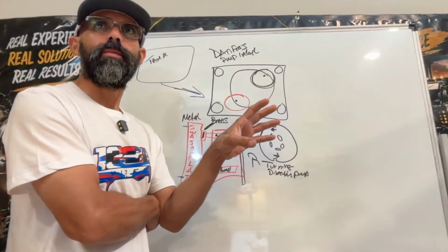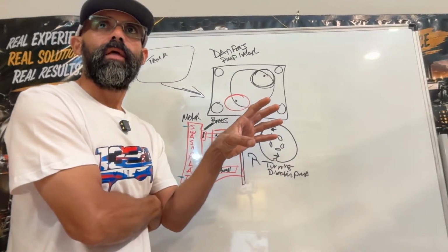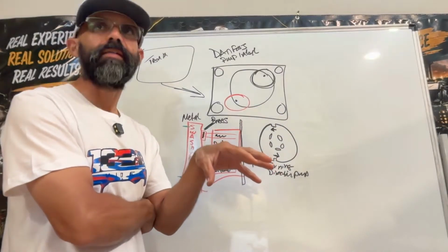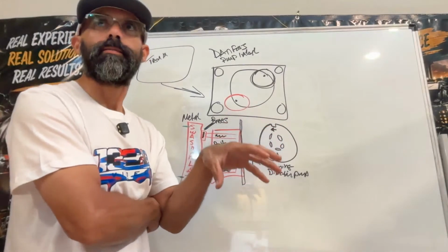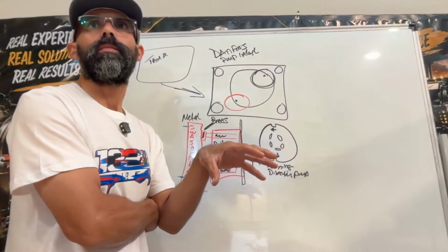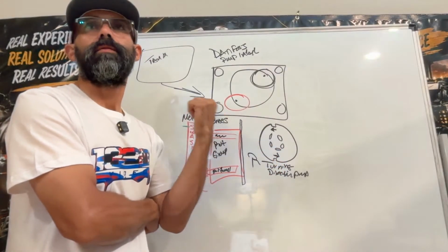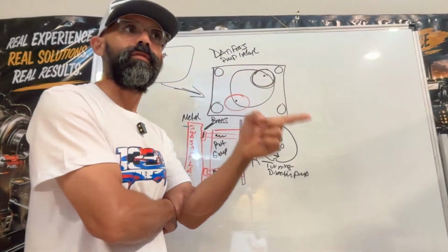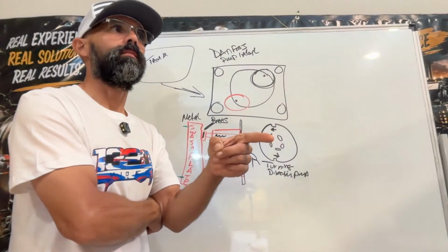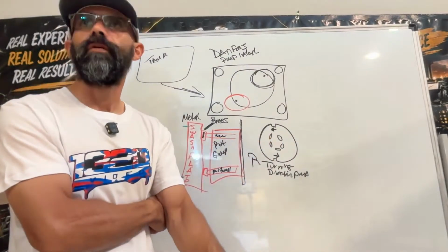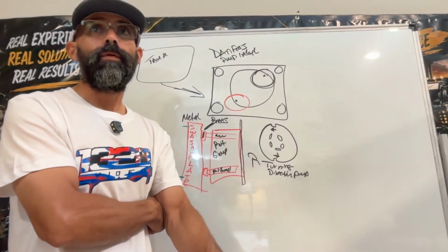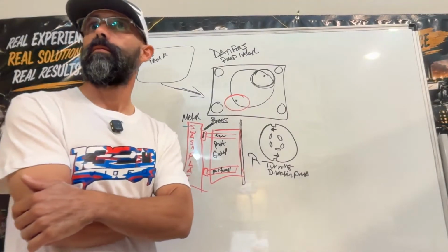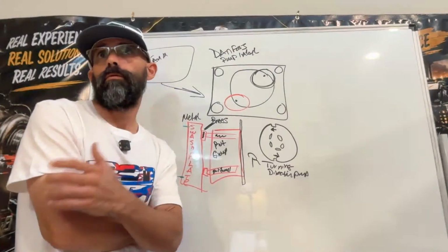when you're ready to assemble the pump, just lap it. Make sure you do it properly. Expensive? Yes, it is expensive, acquiring that equipment. But it's going to save you time in the long run. You're going to know this was done in a professional way, completed, and that it's not going to fail. But if you don't do it right, you might have the equipment back in a week or maybe the next day, because maybe you didn't lap it.